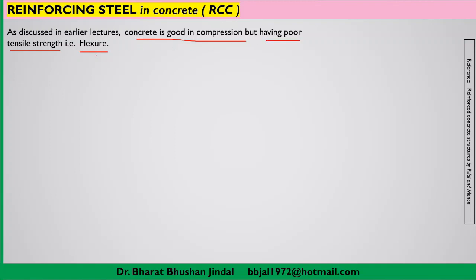Whenever there is a structural member made up of RCC, it will be subjected to flexural behavior, that means bending behavior. So when loads and forces act on the member, it will be under flexure, that means under bending, and when a member is getting bent, one part of the member will be under compression and the other part will be under tension.